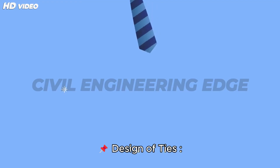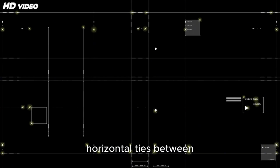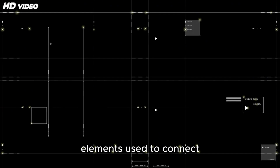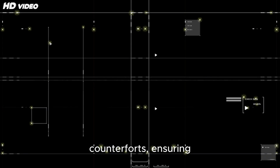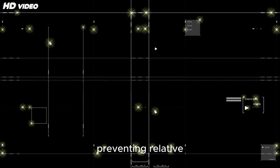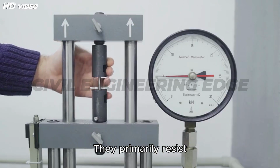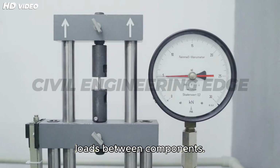Design of ties. Scene: reinforcement detailing showing horizontal ties between counterforts and stem. Ties are reinforcement elements used to connect the stem and counterforts, ensuring monolithic action and preventing relative movement between the wall parts. They primarily resist tensile forces generated due to differential earth pressure and distribute loads between components.